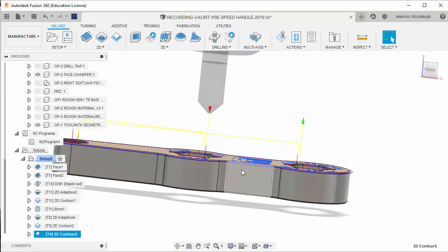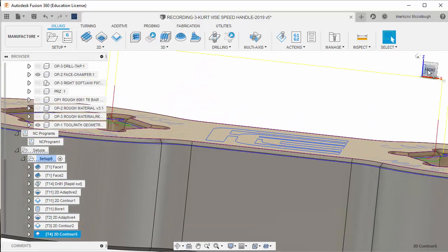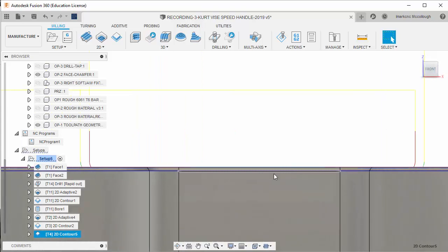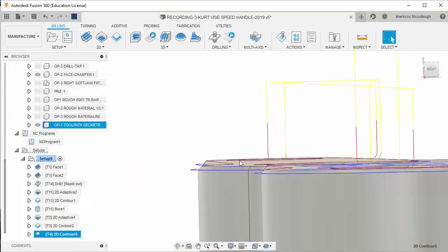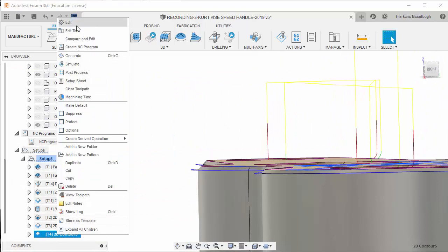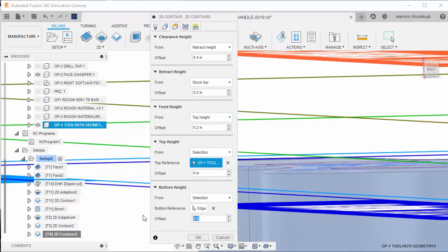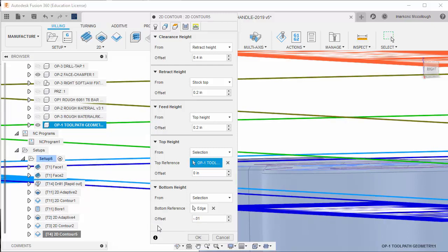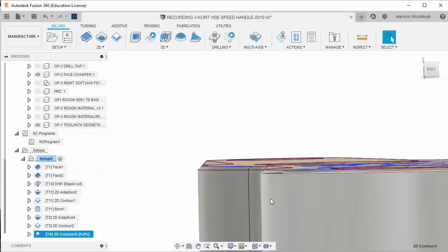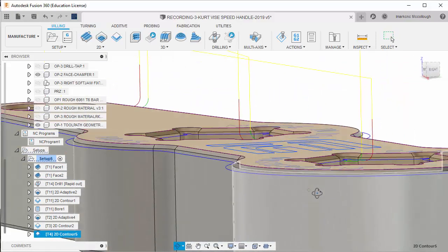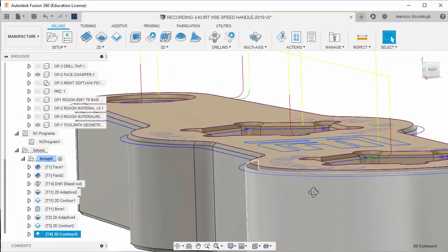And if you look at this toolpath real close, we're right at that line. I want to drop it down. So as we drop it down, it's going to move it away. So I can come back here and edit this again, choose edit, come back into my heights, and let's just add a -10 thousandths out of that. Okay, and you can see it kind of dropped there. Now my toolpath will be below that, so I don't get any sharp edges or anything like that.